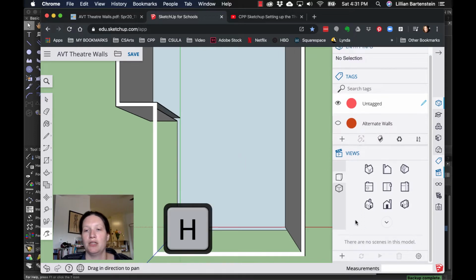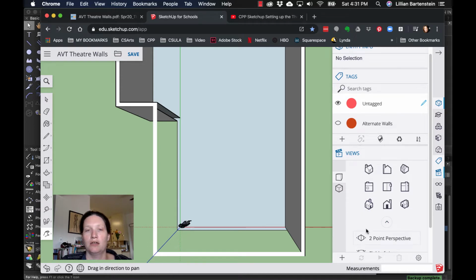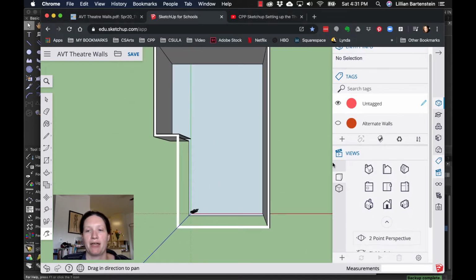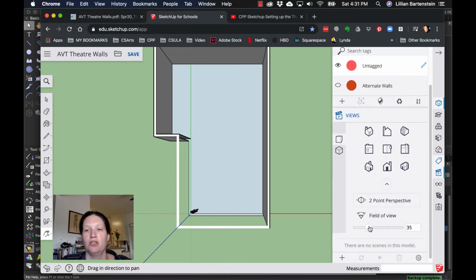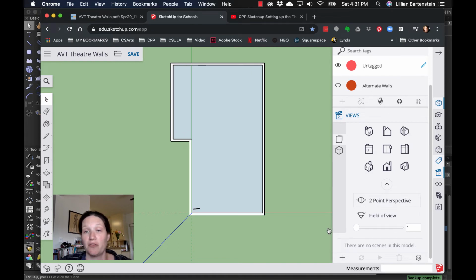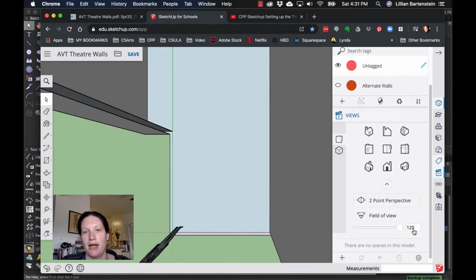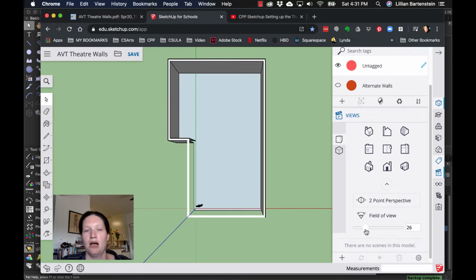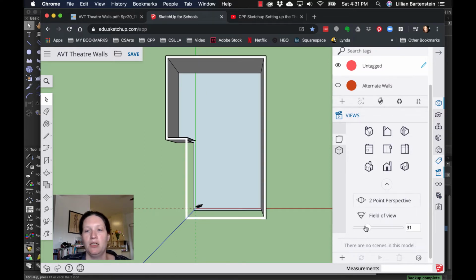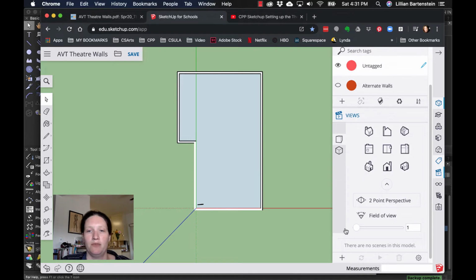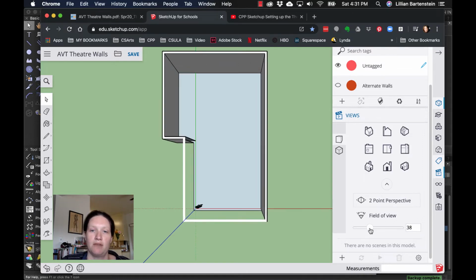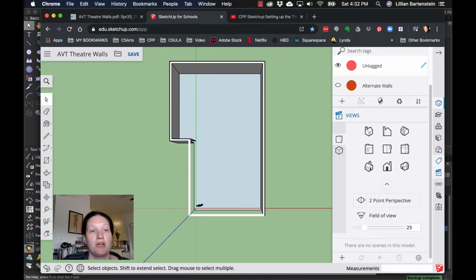So the thing that's going on right now is your views are set up to have a perspective on them, okay? When you click this little twirly downy thing, then you can change it to have no perspective, and now it looks like a regular ground plan, or you can give it like a wide angle lens, okay? I'm gonna leave it a little bit perspective-y, but for me, this ground plan view is super helpful because I'm used to thinking about drafting from a ground plan perspective. So I'm gonna grab my rectangle tool again, and I'm gonna add in this rectangle for the risers, just like that.